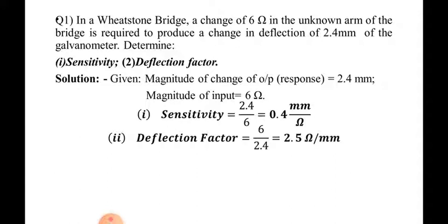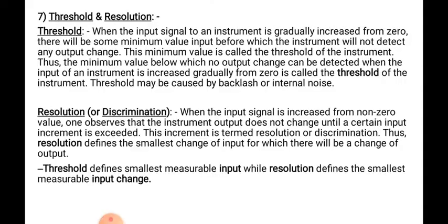So that is the answer for both questions. Sensitivity is 0.4 millimeter per ohm and deflection factor is 2.5 ohm per millimeter. Everyone will understand how the calculations are done here. Next, we will study threshold and resolution.